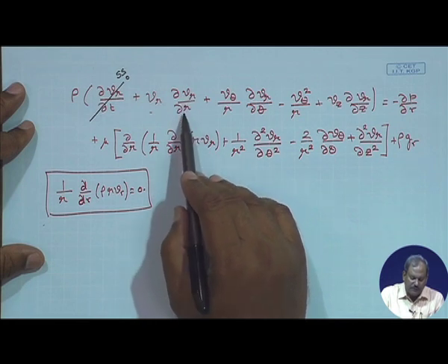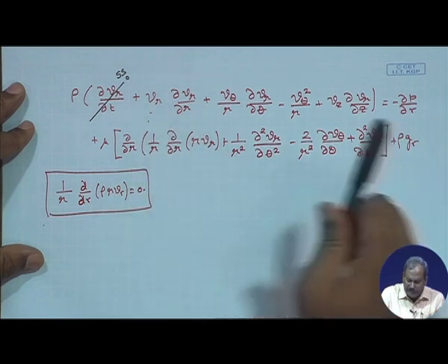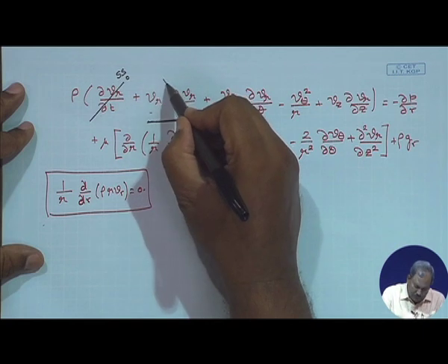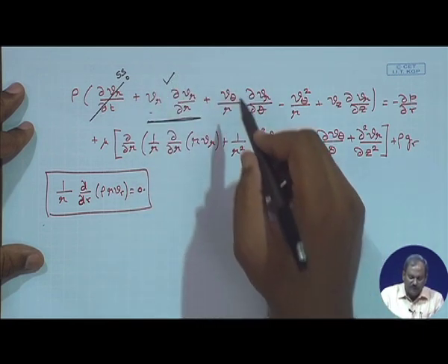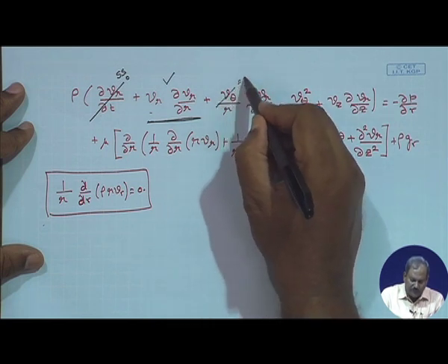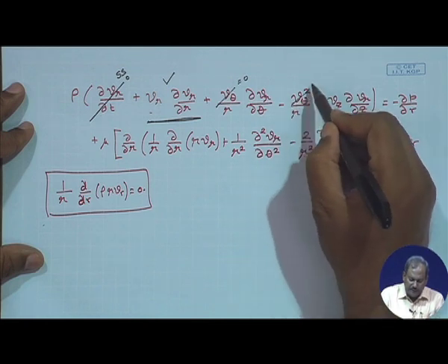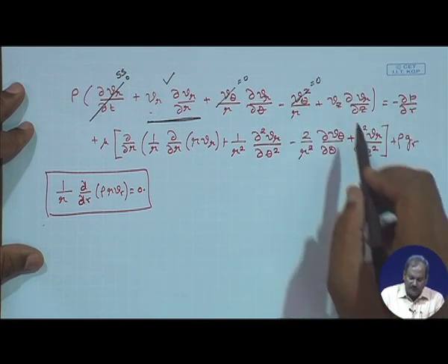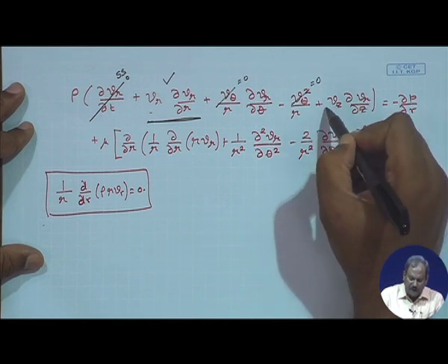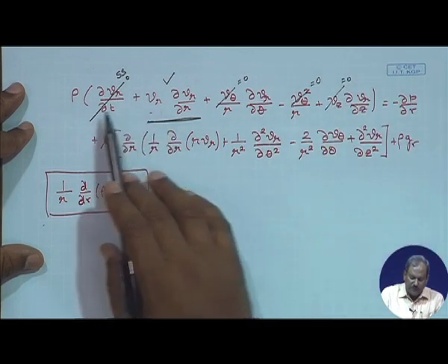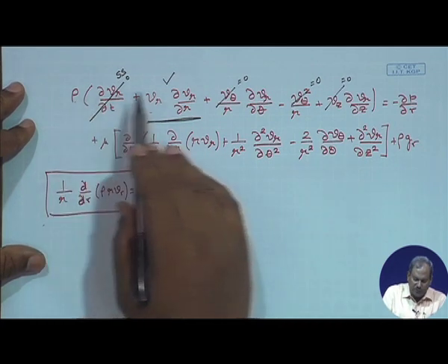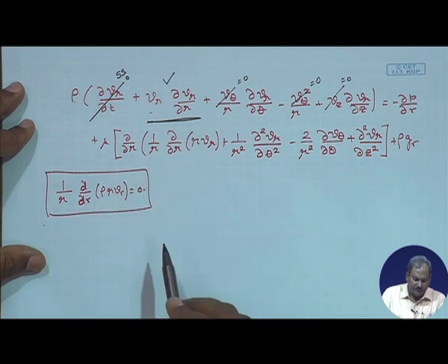So, Vr varies with r, therefore we cannot say anything about it, we cannot equate this term to 0. So, this will remain in the governing equation. Here we have this term, the V theta would be 0, and in this case V theta would be 0 once again, and even though Vr varies with z, however Vz is 0. So, therefore, of the entire left hand side, the only term which remains is rho times Vr del Vr by del r.